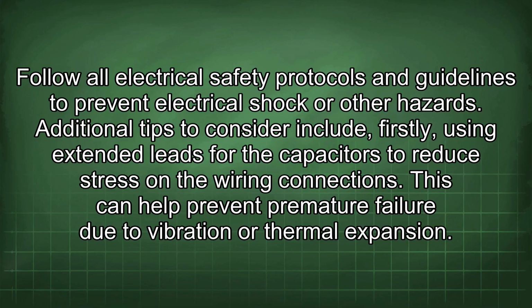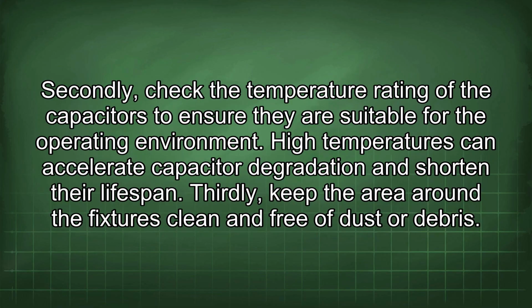Additional tips to consider include, firstly, using extended leads for the capacitors to reduce stress on the wiring connections. This can help prevent premature failure due to vibration or thermal expansion. Secondly, check the temperature rating of the capacitors to ensure they are suitable for the operating environment. High temperatures can accelerate capacitor degradation and shorten their lifespan.